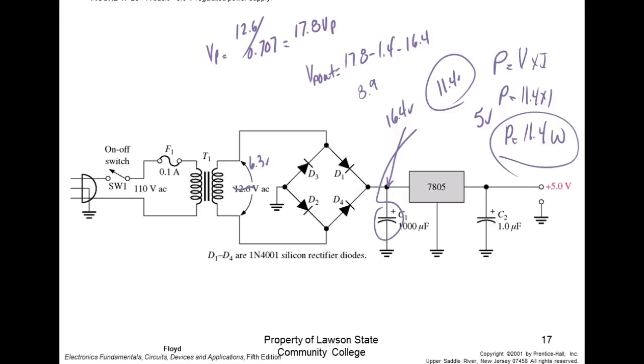And if they drop a voltage and you push current through them, they're going to do what? They're going to get hot. So what you're trying to do on these linear power supplies is make sure you use the right transformer. Either that or suffer and heat up your supply. These guys, by the way, have thermal detection circuits in them, so you can't hardly burn them up because they'll shut themselves off if they get too hot.